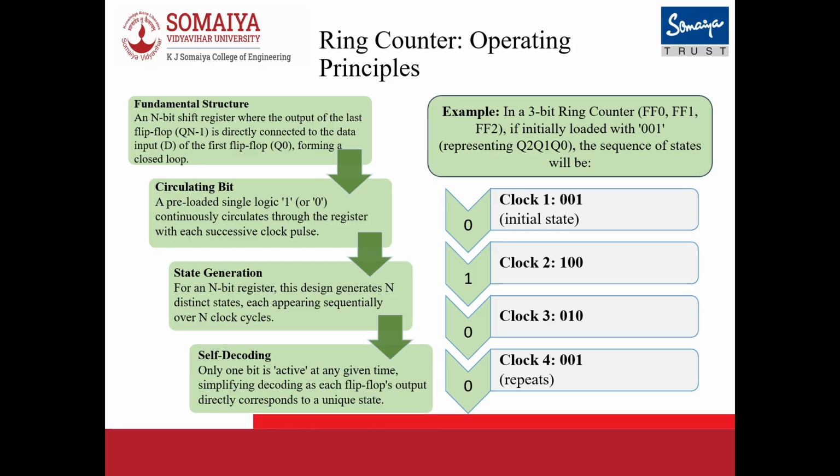Before the operation begins, we need to initialize the counter by loading one of the flip-flops with logic 1 and all others with logic 0. After this, each time the clock pulses, the 1 shifts to the next flip-flop, moving in a circular pattern.